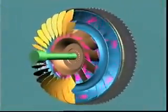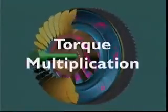The fluid strikes the forward face of the stator blades with a backward force, which locks the stator on the one-way clutch. The stationary stator and the angle of the blades change the direction of the fluid flowing between them. The fluid re-enters the impeller at high velocity in the same direction as impeller rotation. It strikes the back of the impeller vanes with considerable force, giving up energy to assist the engine in turning the impeller. This provides torque multiplication.